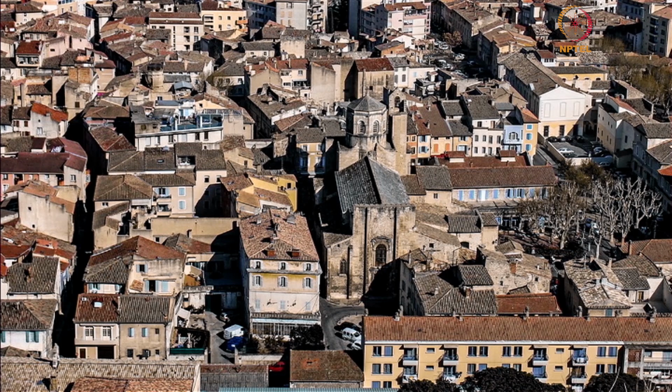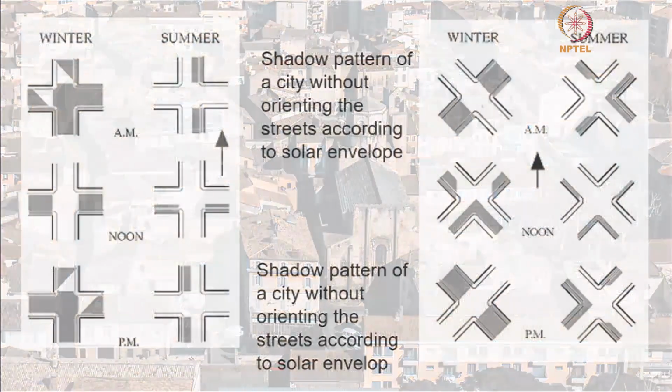The concept of a solar envelope was developed by Ralph Knowles. It can be accessed for more sophisticated solar access at city level. So the solar envelope guarantees solar access to properties by regulating construction limits, and they are derived from the sun's relative motion. Buildings within the solar envelope would not shadow adjacent properties during a predefined period of time, usually the critical energy receiving periods during the year. These guidelines are especially effective at the city planning level.